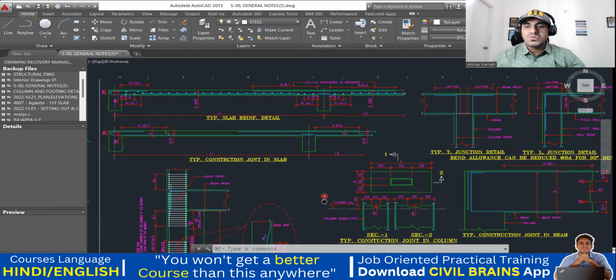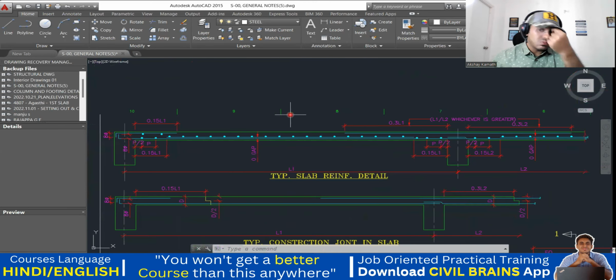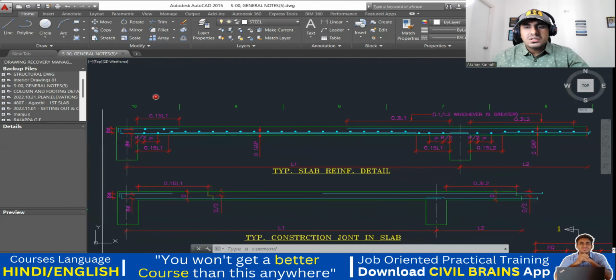And now we'll go finally to the slab portion. I'll finish the slab also. The slab is again simple, like we do for the beam. The same is the slab. Again for the slab, you'll be providing top left extra, which will only go 0.15 into L1. You know that.